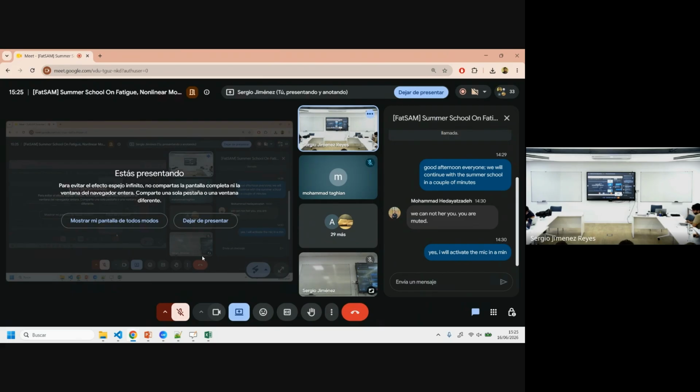You can see the piece here. MDPA and JSON written. So the files that I gave you have been modified. This is basically what I'm telling you. So what you should be doing is downloading once more and decompressing once more the info that I sent you to obtain the files that I sent you. And instead of clicking on calculate, you should go to Kratos and run without regenerating the files. Or basically, as I've sent you not only the geometry and the mesh, but also the results of the calculation.